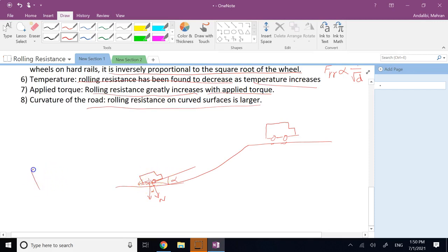What you have really is, if you have a system like this, you have two normal forces here and here. And when you're going on the hill, the distribution of the load on the two tires, if we call it N1 and N2 here, the difference between N1 and N2 depends on the weight distribution in the car, okay, depending on where the engine is and everything.